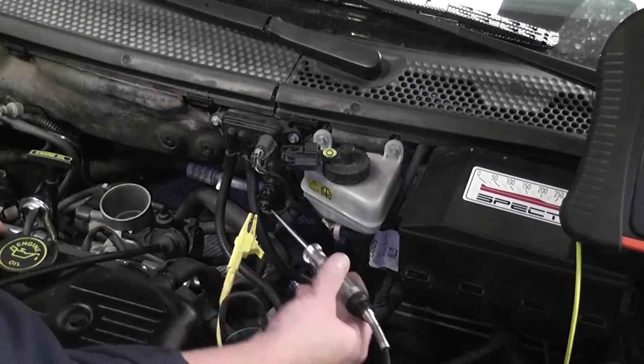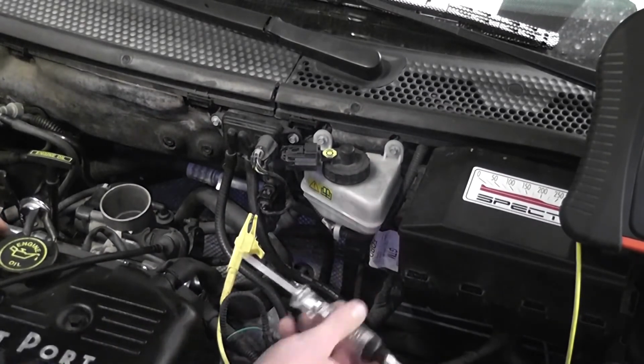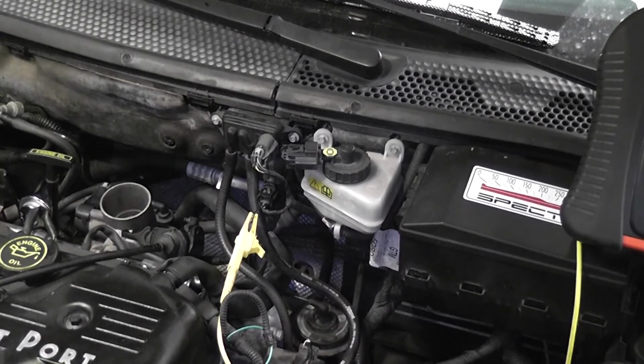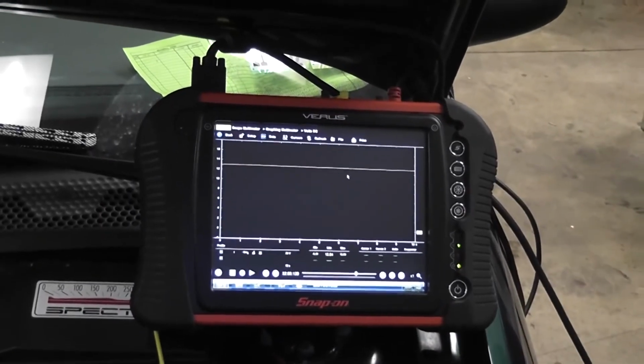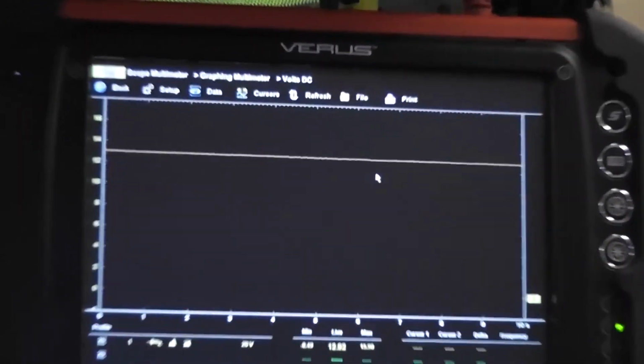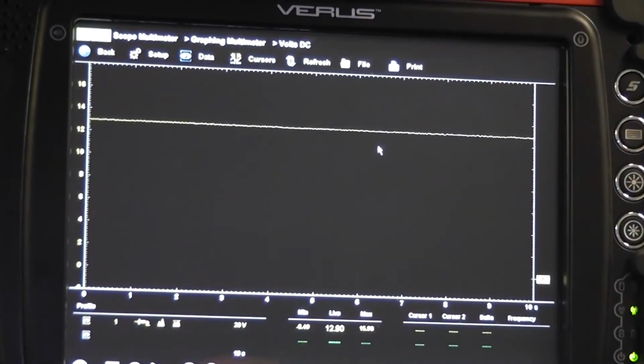And do the test first. Stalled the car out. There's no problem with that. It should get real rough or stall, and what that tells you, the solenoid's functioning, the valve is opening. One last thing we want to look at for that test, make sure the DPFE voltage is rising. So I'll get you back to the scanner. I'll get you on that DPFE voltage, and then we will redo the test.